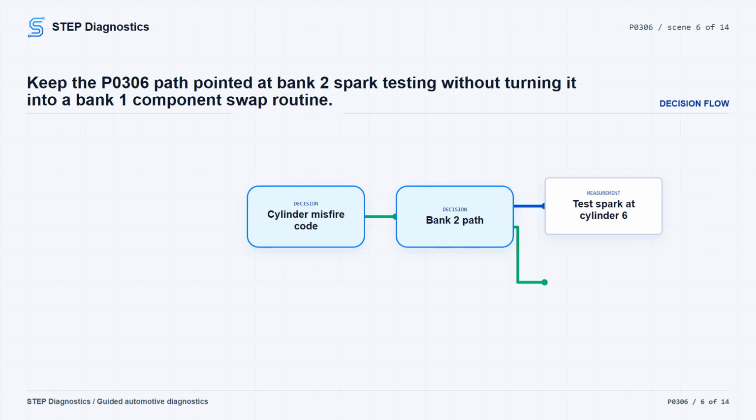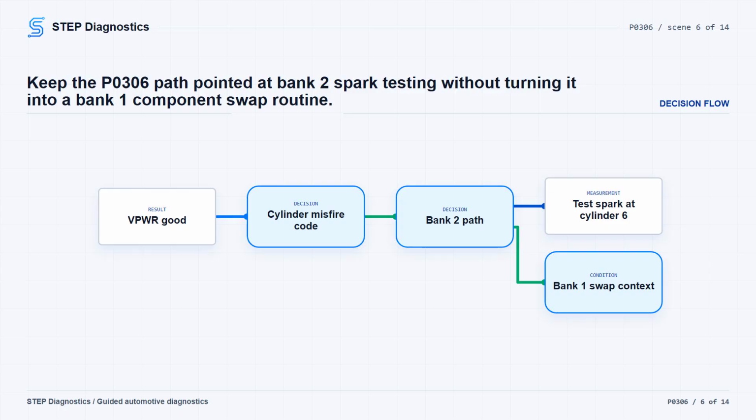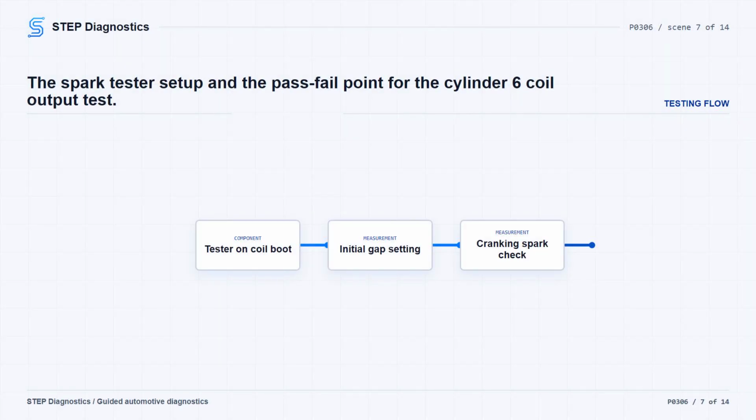Disable the fuel pump by removing the fuel pump fuse, disconnect the ignition coil from the spark plug, and connect an adjustable ignition spark tester, THX458, or equivalent to the coil boot. Set the tester to 40 kV and crank the engine 3 times. Then set it to 25 to 28 kV and crank while watching the tester. A correctly operating ignition system only needs to show spark in the 25 to 28 kV range. If spark is not present there, install a new coil or COP, clear the PCM DTCs, and repeat the self-test.